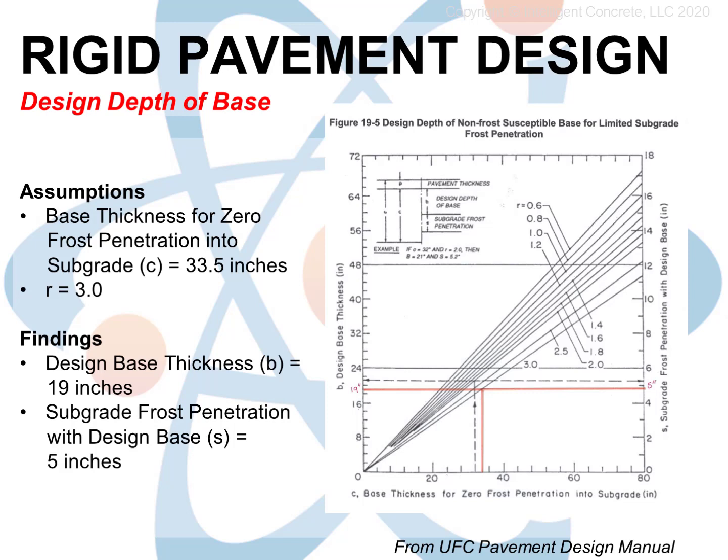For our light-duty roadway, where we figured we needed 17 inches of compacted base, we would need to place an additional 2 inches of base and subbase to limit any additional frost penetration to 5 inches. Or we could place a total of 7 inches of additional base and subbase. That is the 2 additional inches plus the 5 inches of frost penetration, and there would be no penetration into the frost-susceptible subgrade, thus virtually eliminating any danger of frost heave.